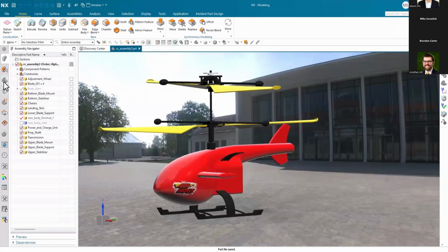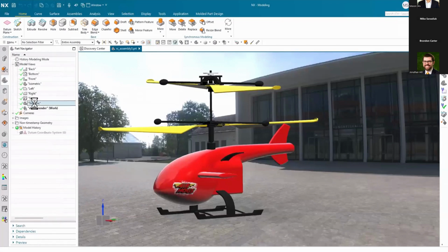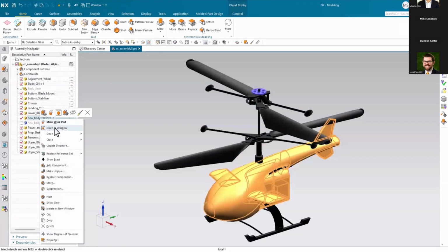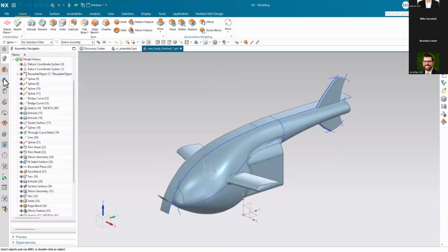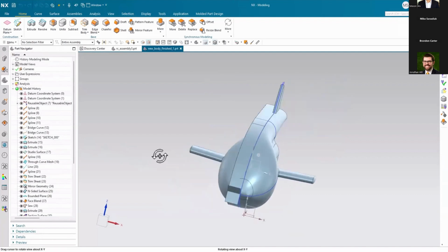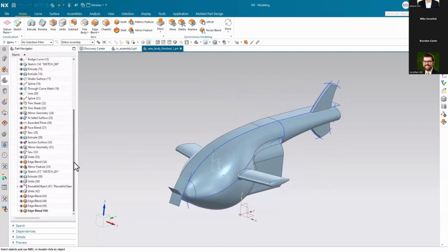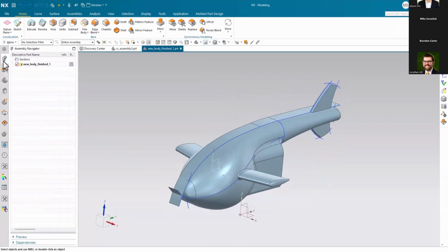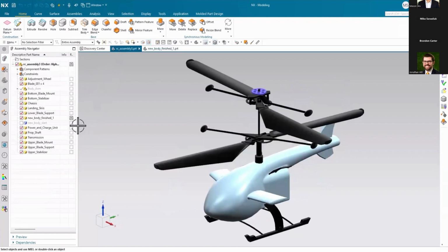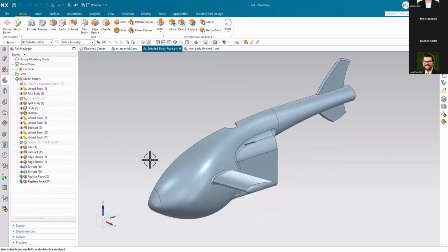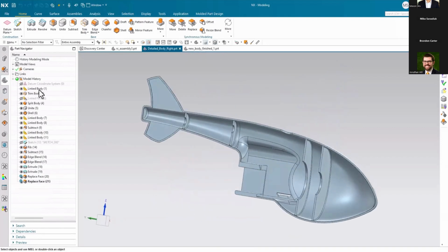So let's take a look at the next phase of this, right? Inside of this, we can go ahead and have, again, our segment where we want to drive the right and left hand side of the part, right? The plastic parts. And so you saw me go through how to develop all of this with our advanced surfacing. We'll show you a little bit about how we get that and go forward into the detailed design. So here we have a sub-assembly, and the way we drive this is we use something called geometry linking. So I can geometry link curves and surfaces and datums and all of that into this detailed component.